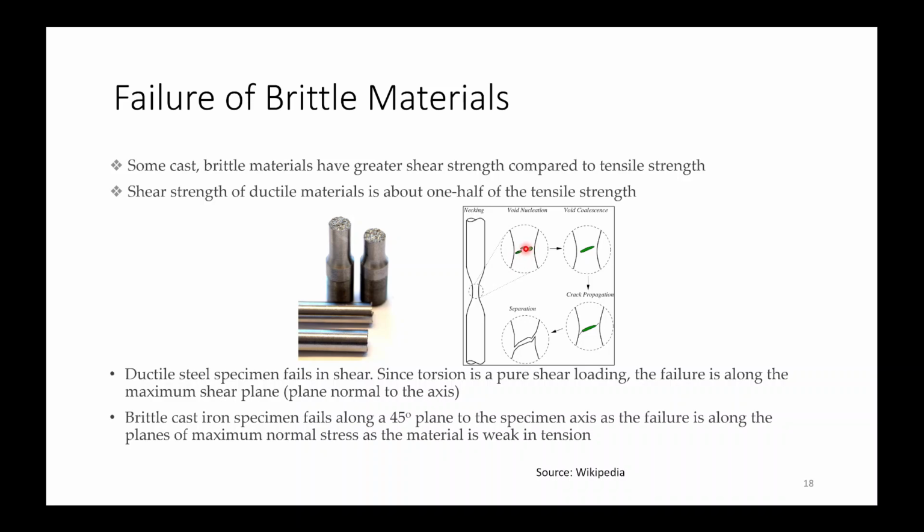So if I'm applying compressive type of load, then it will act like a cold welding type of phenomenon, right? I'm compressing it from both edges. So these cracks will try to get shut in that case rather than opening. And when I am applying tensile type of loading, then these cracks will further open and crack propagation is more likely to take place.